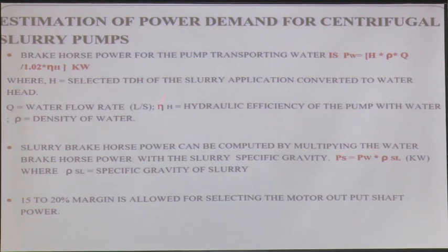Now, this is for clear water. Now, what to do with the slurry? Do not do anything, just multiply this power PW with the specific gravity of the slurry. You get the power for the slurry transportation. This is the brake power, that is power at the pump shaft.